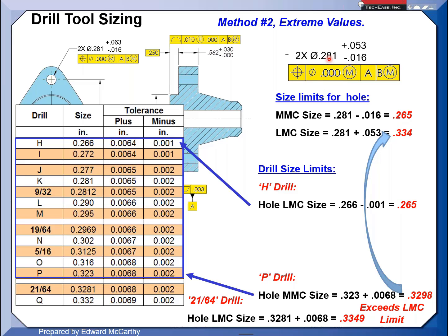I've had it happen because I've done a part myself where maybe we had a value in here, 20 thousandths. Then all of a sudden I did zero. They think, oh my God, Ed wants a perfect part. No. That tells me right away they never knew what this M meant. Yeah, but it's very hard to persuade people. I've had to do that numerous times myself, and go out to suppliers and actually teach them what zero at M really means.